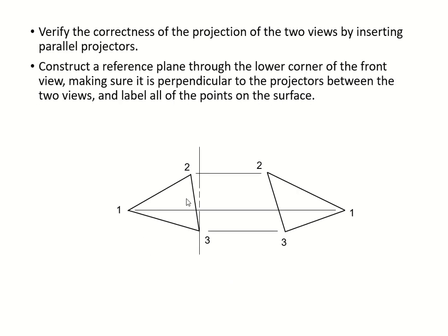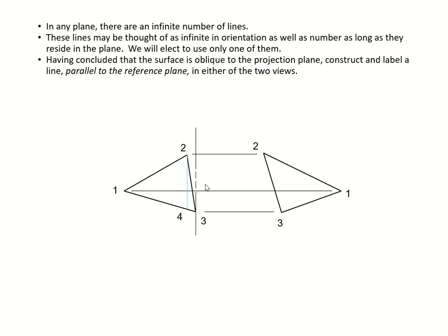So let's get into the next step. Since there isn't one, we're going to put our first fold line close to our front view. Usually put it at the edge. Don't forget the depth. This is your right side, so there is a depth every time we do the dimensioning from the first fold line to all of your points. We do the same thing, point to point. Draw all of your projectors. Projectors are these lines. Then look at this.